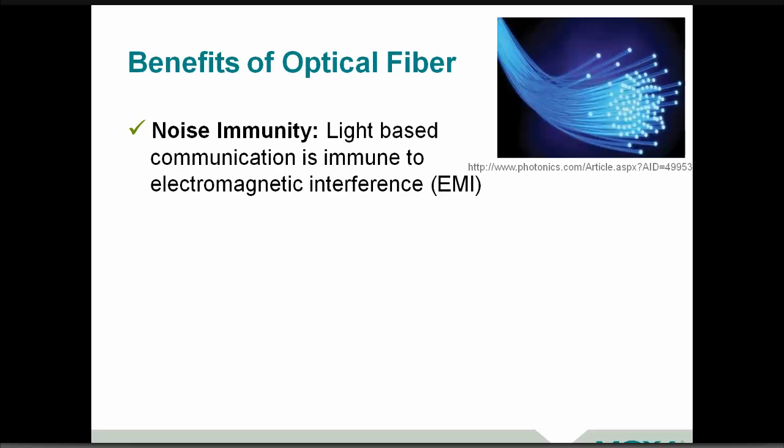Now, just a couple little basics of this. Without delving into the magic of the refractive index and fiber, there are some great properties of optical fiber. Number one, and a lot of you probably already figured this one: if we can move this to pulses or waves traveling down an optical fiber, we get away from having to worry about electromagnetic interference. Arc welders, RF sealers if you're doing packaging equipment, radios nearby, all of that goes away. You have total noise immunity, which is a great property of using fiber.